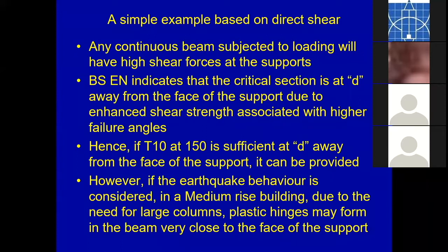But make sure you practice using these codes, using textbooks like Mosley and Bungey or McGinley. If you can't understand the latest Eurocodes, try and understand the British codes with the principles, with the theory. Then you can use books by Allen, Mosley and Bungey, and McGinley, and so on. Learn the British code and then see how it compares with the Eurocode, because Eurocode and British code cannot have so many different things, since we are dealing with the same material.